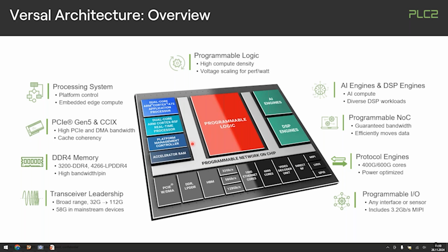But what has been split off from this PS part in the Versal design is really the DDR interfaces, because they are now not bound to the PS part, but they are made available throughout the device with the network on chip. That has certain advantages, of course, because you don't need to multiplex data on these interfaces. You can separate them out. So if you use multiple DDR controllers, they would all be bound with the lowest latency path to your particular logic implementation, and you can have another DDR interface that's bound for your processor and only take care of the least traffic between those.